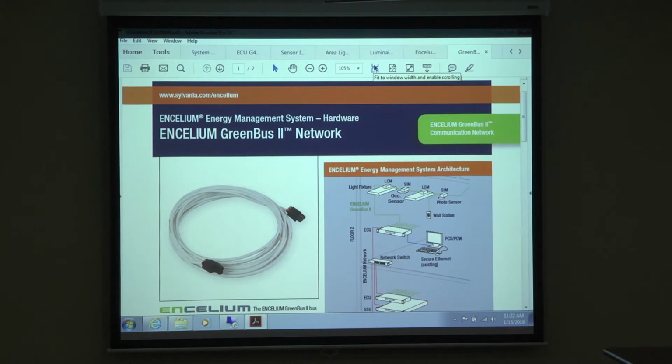And in series circuits like that, you know that once you go, say, halfway and disconnect it, everything downstream has no communication, it won't work. Everything from that point back to the ECU will work fine, right? That's somewhat used for troubleshooting methods also. So if something is happening downstream, you can just physically look at the switches. Is there light on the switches? That means it has power. You go to a switch, there's no light on the switch, something's happening right there. You go in, the cable is plugged out. Plug the cable back in, a couple seconds, it's all working again, right? And the program can show you that also to narrow your search. We can show you that later on, how you narrow your search using the program, right?